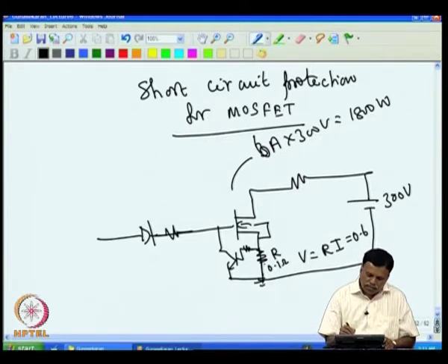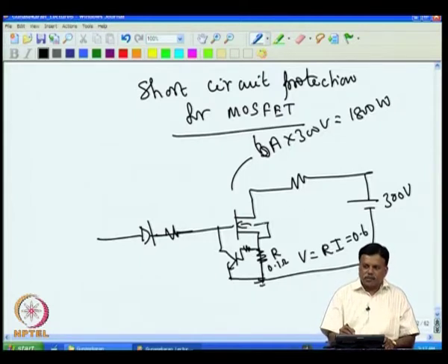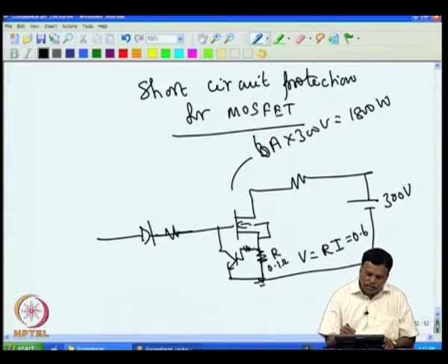So, one should not let this happen. Once this is activated, once you short, you will find this exploding, and the purpose of the protection is lost. What we have to do is this is acting as a current limiter. As soon as this is activated, you see that this voltage goes high because this is shorted, that is why the entire voltage is coming here. So, this point voltage will go up. Once this point voltage goes up, we should shut down the MOSFET. Otherwise the MOSFET will go into the vapor state. So, this is acting as a current limiter.